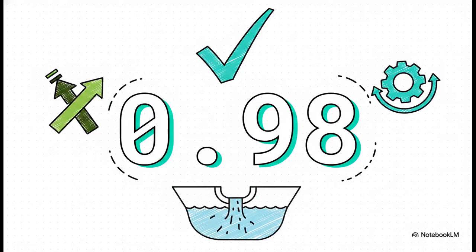And now, the absolute moment of truth. When we divide our actual measured discharge of 0.0132 by our mathematically derived theoretical discharge of 0.0135, we get a coefficient of discharge of exactly 0.98. In the engineering world, a coefficient that close to a perfect 1.0 is incredible. It proves this simple, flat-bottom flume is practically flawless at calculating flow rate. No way around it, the math works.